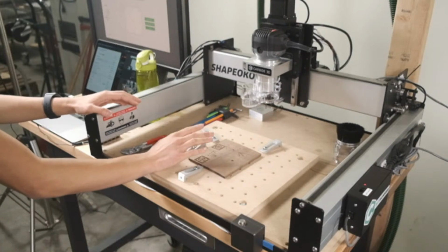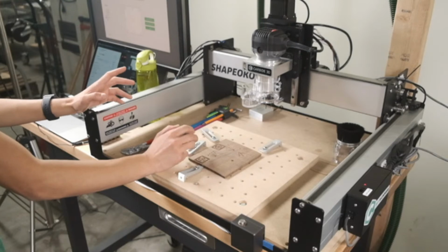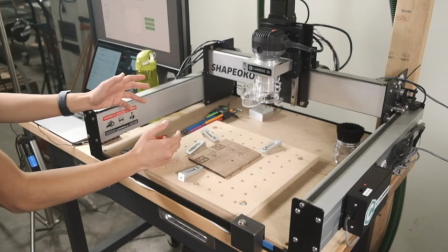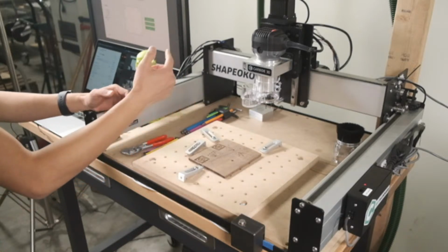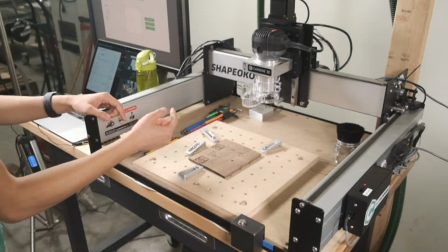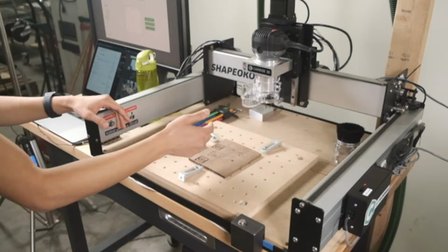Almost every problem you have on a CNC goes back to basically the machine underperforming. The controller, like 99% of the time, works just fine. The issue is that either the motors or the belts or the V-wheels, something in that chain of transmitting the power to move the machine just is failing.